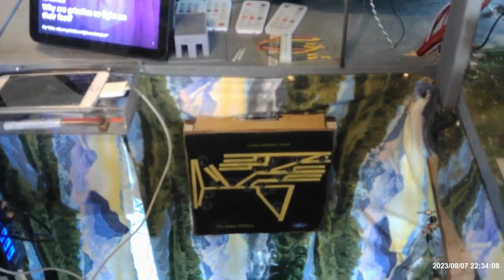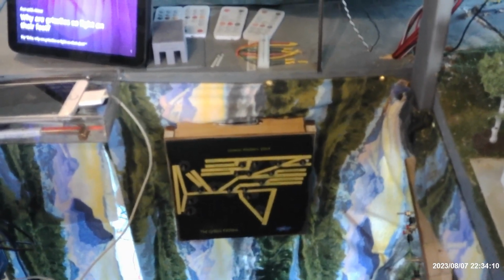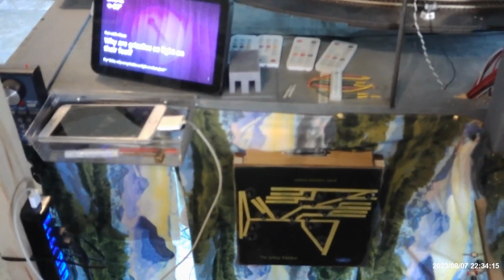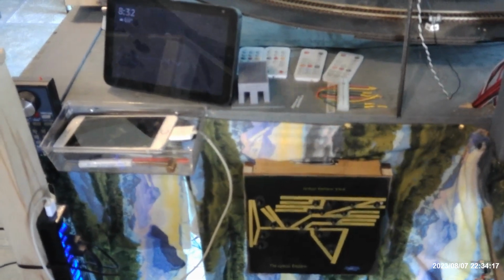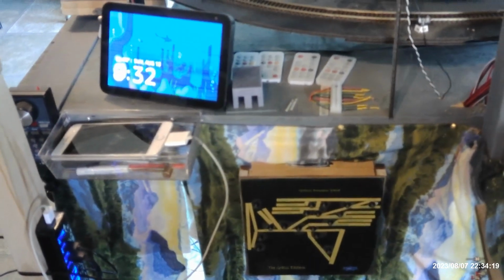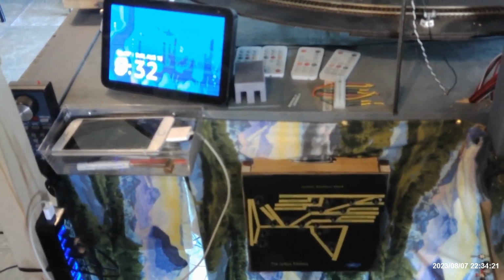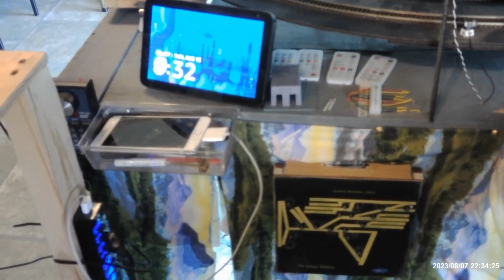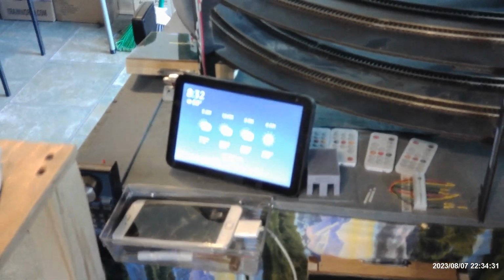So the relay then, once I push the button in, sends voltage down the line to the AIU-01, which then triggers the sensor, which then JMRI says, oh, you've changed, and let's change the turnout on the JMRI panel. So that's just a quick overview.